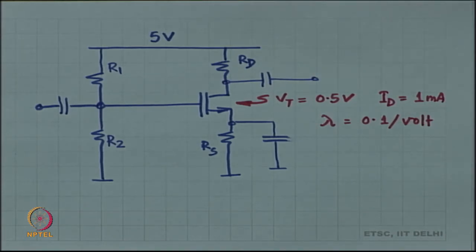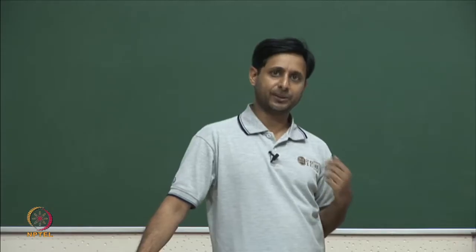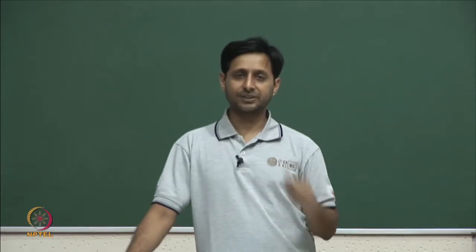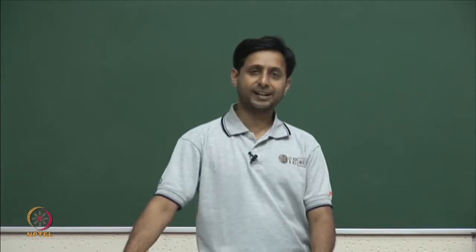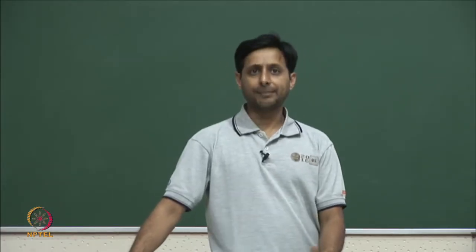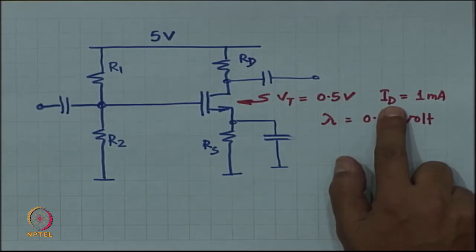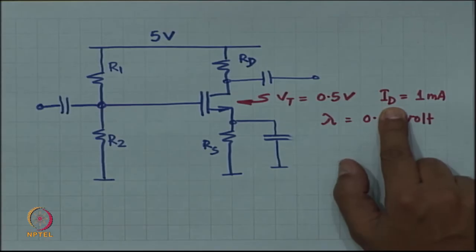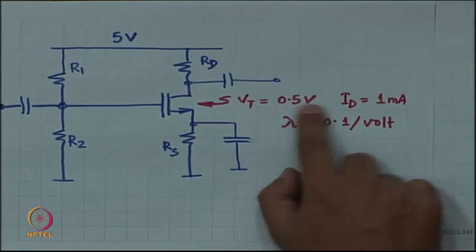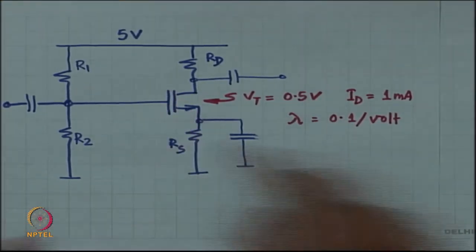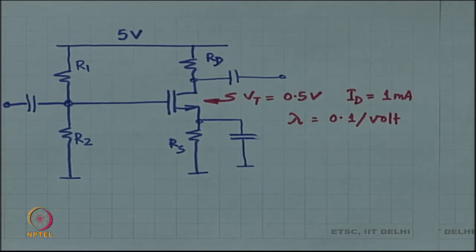Okay. So, the MOSFET has two basic parameters, one is GM and the other is GDS or RDS, right. GM effectively, if you know ID, if you know VT and if you know something a little more about the MOSFET like K times VGS minus VT the whole squared, that is ID.